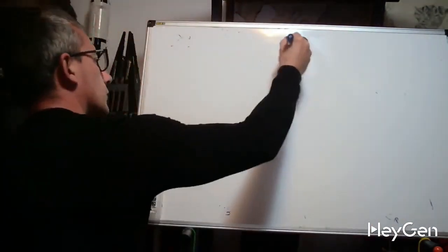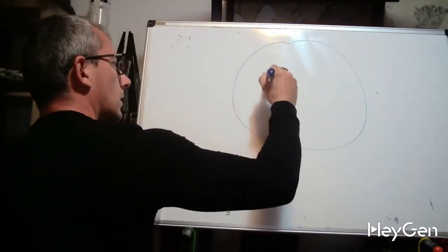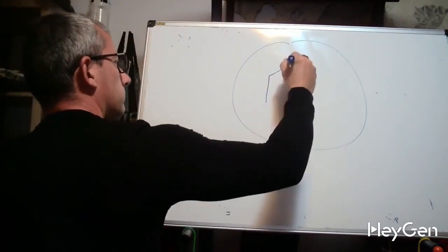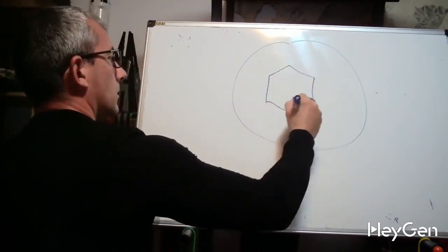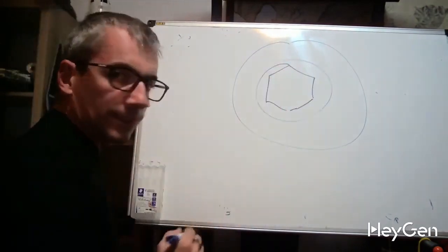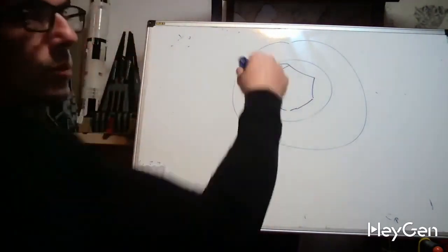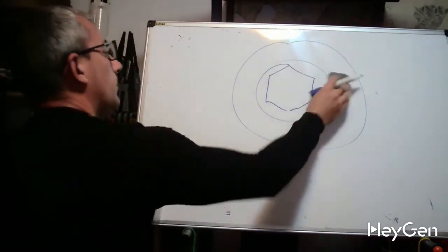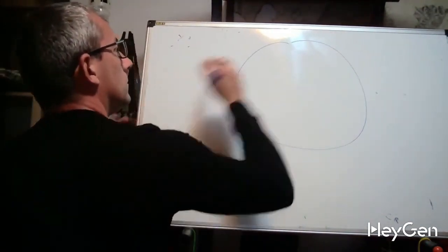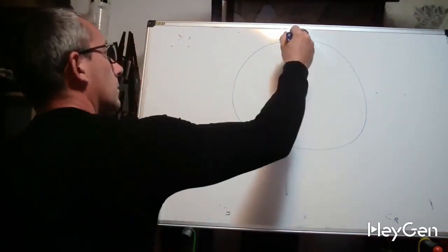In the process of machining, when dealing with a situation where the workpiece has a significantly large diameter and there is a need to create a hexagonal shape precisely in the center of the material, I will not choose to remove all the material from the center using a milling cutter, as it is not the most efficient method.